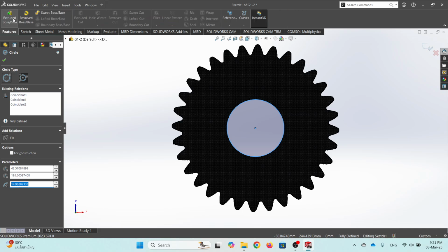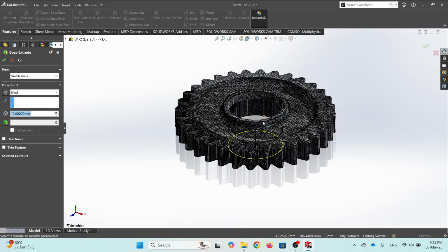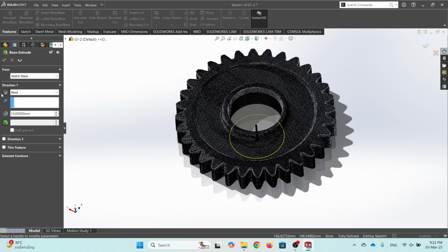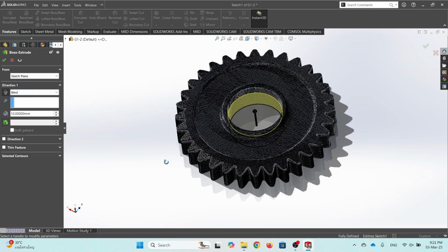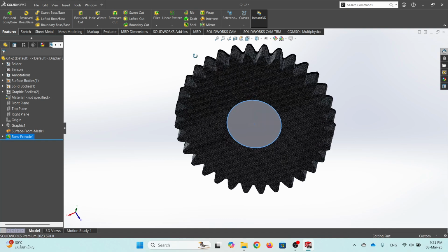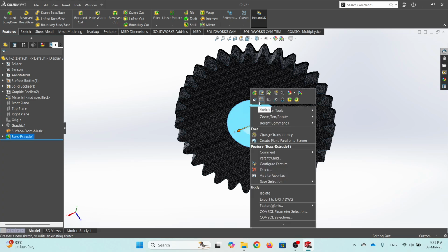And then we have to extrude that onto the inner side of the hole, so you can see that it is actually the opposite side. So we're gonna click this one right besides the blind key, and then we're gonna extrude inside, and then we press OK button. Next we're gonna create a pin out of this shape,